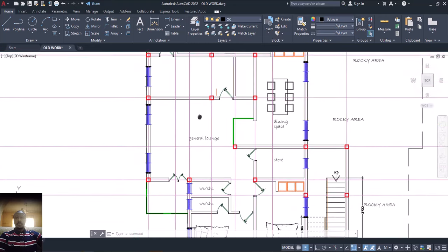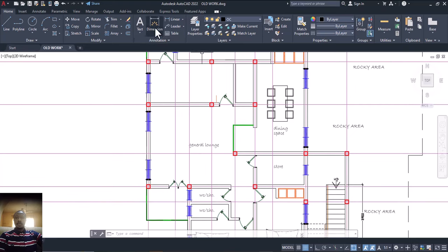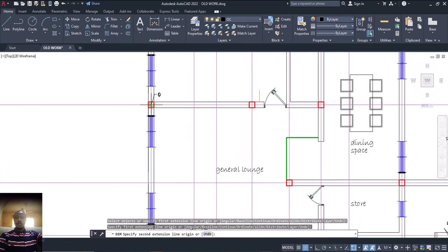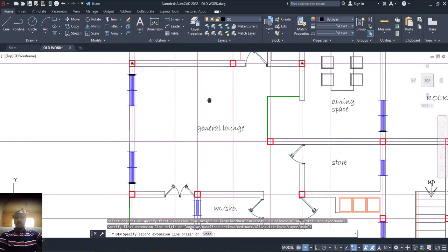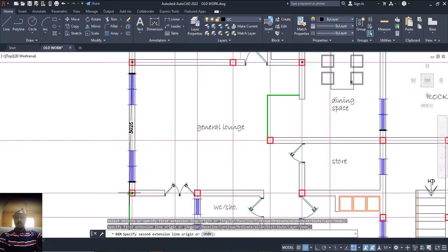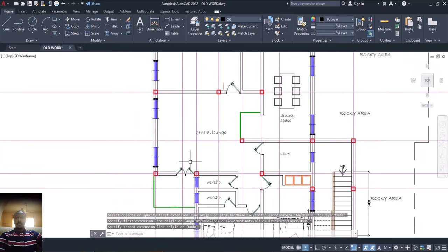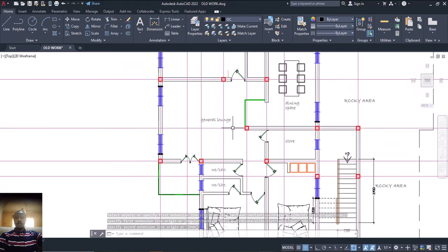So now coming to this place now. I'll take this place like this. Also, from here to this point, 6.7, the same thing. And coming to this place is what? 5 point something, which means 30 square meters. Is that okay? 6.8 is more than 5 point something. That's already more than 30 square meters. Since it's more than 30 square meters, I can decide to break this panel.